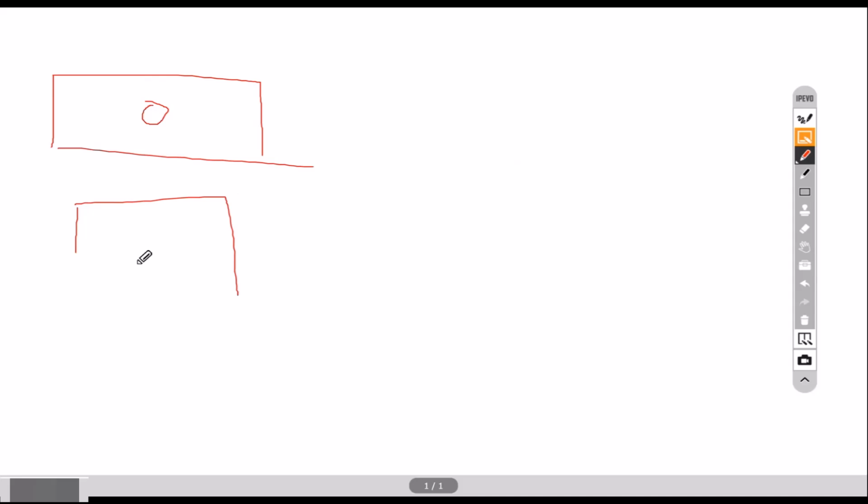Like, if you remember, in the first session I made one rectangular body, right? I made one part where the hole was at the center of the face initially. But when I edited the dimension, what happened? The hole moved over here, right? So if dimensions and relations are not made properly, meaning I have not defined the position of my part properly, this will happen.